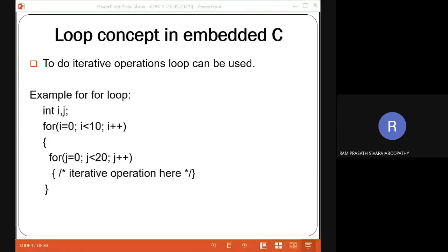Can you suggest suitable data types for the variables? If I am always going to use 10 and 20 in this function, can this reduce the hardware resources used in the microcontroller? Yes, we can use a character variable, as the values are 10 and 20.